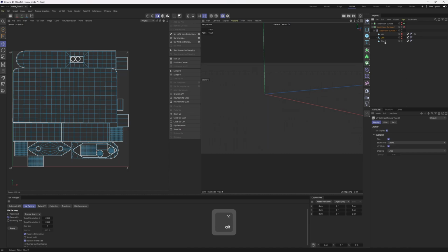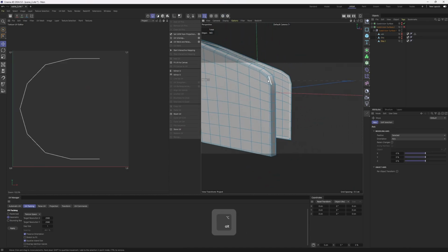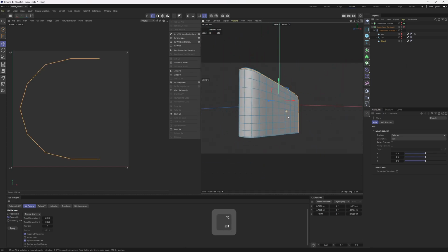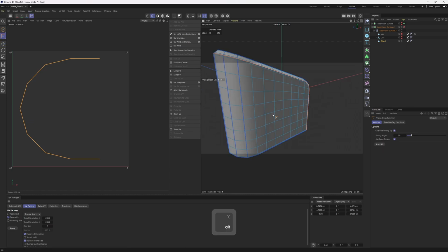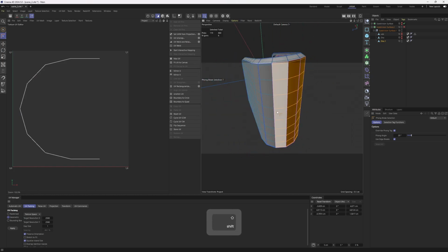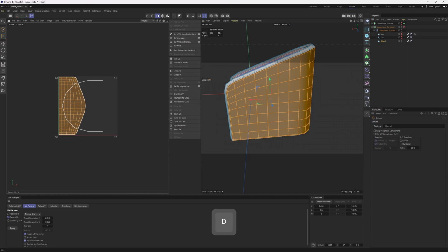Now the other one, let's hide this one, turn off solo mode, select them all. So you know what to do. Just select these sharp edges, or you can use the same methods. Fill selection tool, UV unwrap. Of course, you need to be in polygon mode. So Alt and Shift, select these polygons, and click on UV Unwrap. And move that away, or you can hide it.